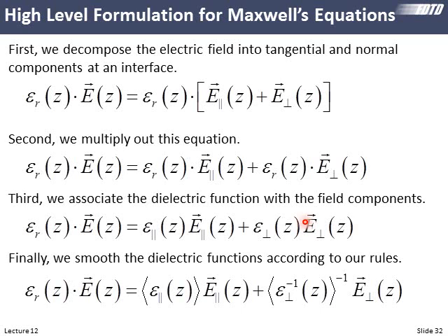which really helps things, which means we do the double reciprocal thing to this epsilon perpendicular. We take the reciprocal of the permittivity, blur that reciprocal function, and then take the reciprocal again. It's kind of like we just blurred epsilon, however, we get slightly different numbers doing it this way. So we start off with the same epsilon for parallel and perpendicular, but we've blurred them differently. We apply the direct blurring to the tangential component of E, and the perpendicular blurring to the perpendicular component of E.